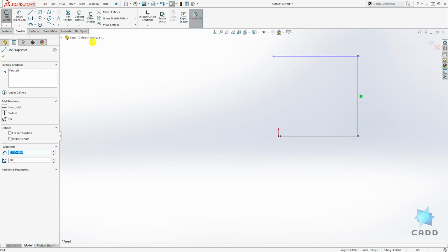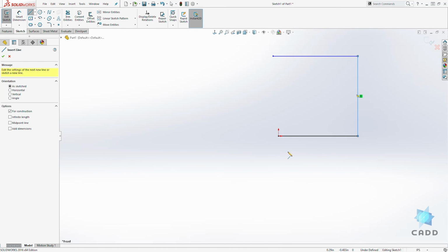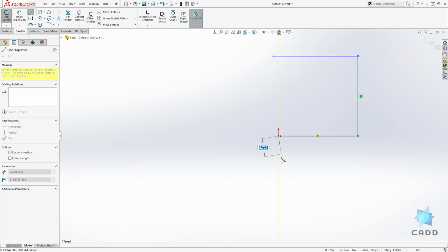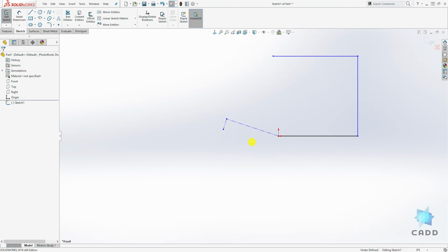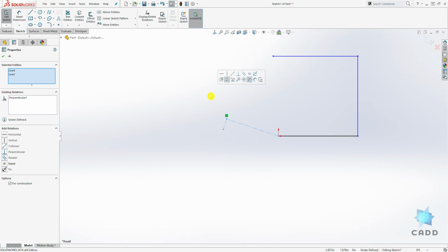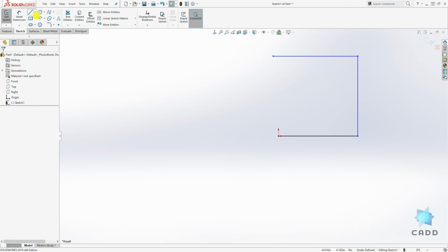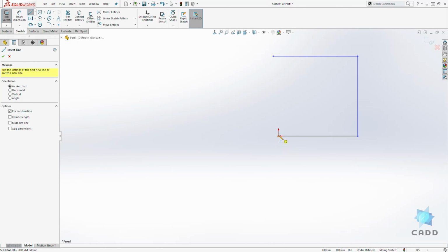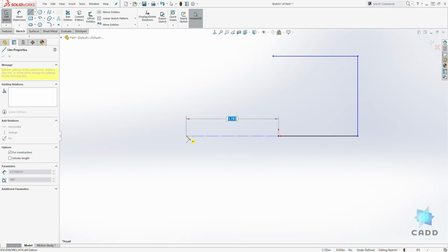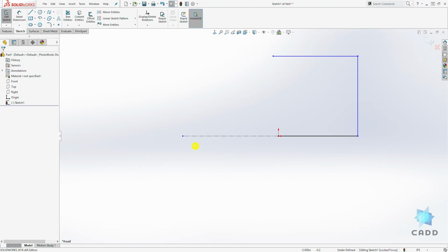And the second type of line is a center line. What a center line means is that when you click on your first point, it will draw a line that is a center line, meaning it's a construction line. Let me delete that and try it again. So the drop down center line, I will click that and draw it, drag it out this way and click, and right click to select.